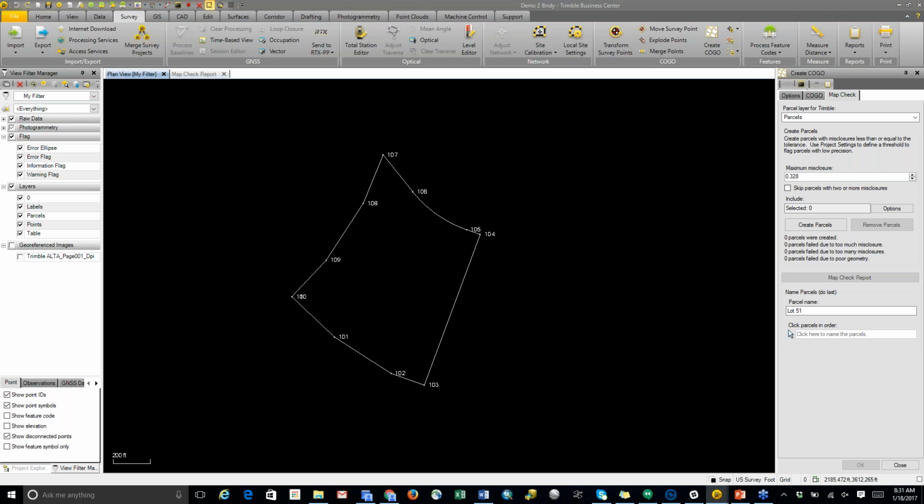Okay. Well, I'll back up a little bit. Where I have my lot, I've finished entering in the information for this parcel right here. I'm sorry if I go back and forth with terminology. Back to the misclosure right here, we can enter in this information if we want this to be closed within 0.02 or less than a centimeter. Then this is where we would change that.